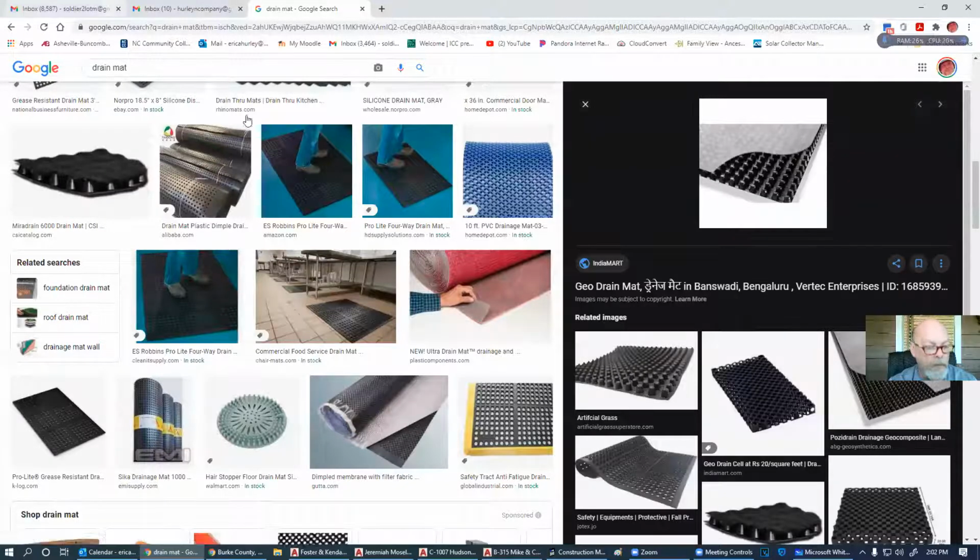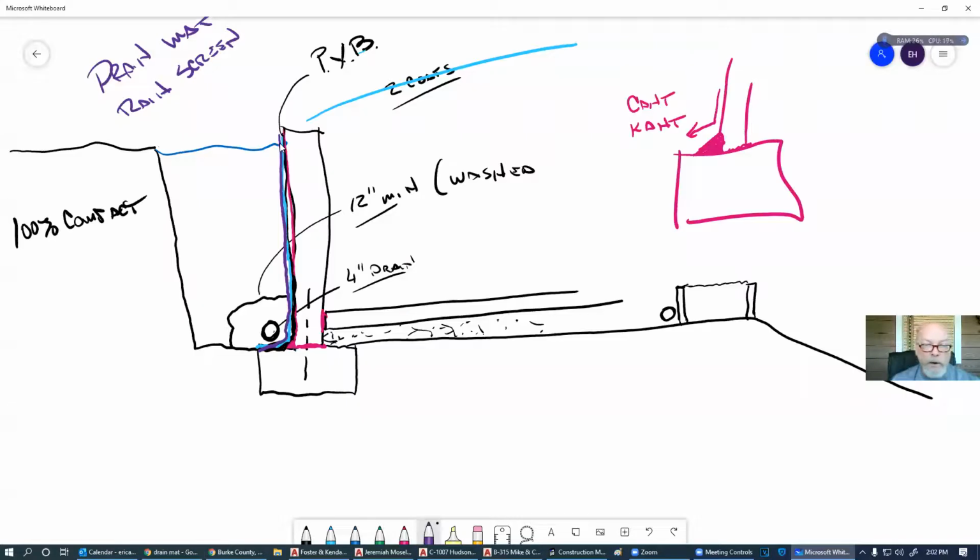All right, now, why would we do such a thing? Basically, why do we put this here? We put this drain here to make a less dense place for water to gather, okay? So this is compact. This is 100%. We'll say that this is, say, 50%. We'll say that this stone down here is 25%. And we're going to say that that is 0%. So that's where the water's going to go.